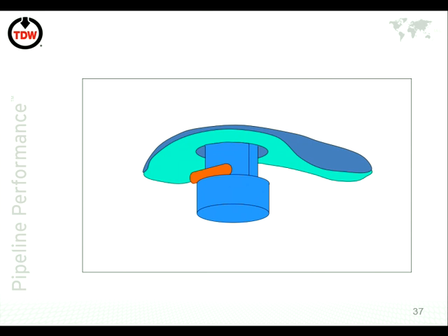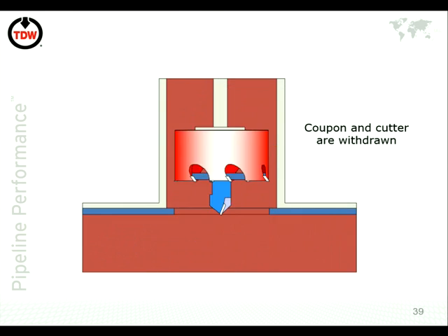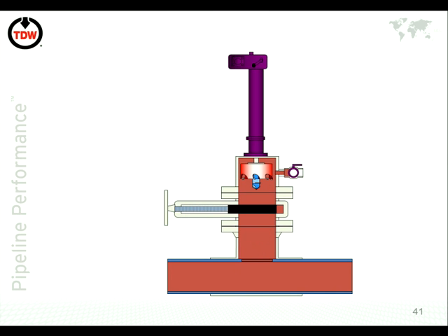After the hot tapping, you said the last stage of the hot tapping, we need to bleed and we need to purge. Yes. So basically, you have to vent off here. So that's the light blue colour there, the product, whether it be oil, whether it be gas, or even high pressure water. You still need to... Well, but you've sealed the operation.